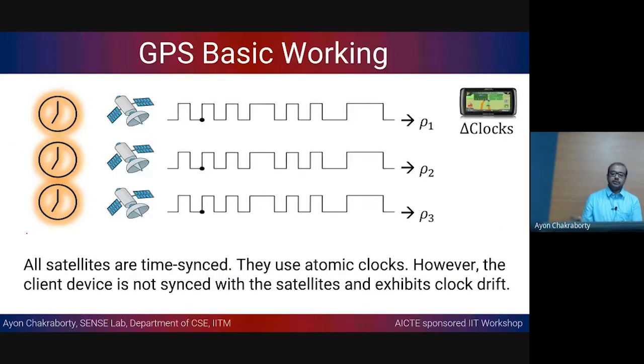Okay, so in the real world, how things work is that the clocks you are using in these GPS devices are not very expensive ones, right? They will have some clock drifts, they are not perfectly going to always be time synced, unless you take some special precautions about it, whereas the satellite clocks are all time synced. Okay, so when you are trying to communicate from a satellite to a receiver, that has to be aligned in some case, whereas all the satellite clocks are time synced.